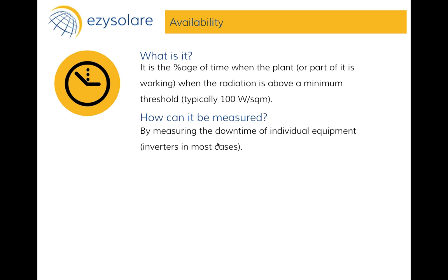Now let us look at how the penalties will get covered because of this dip in performance ratio. So the expected PR was 78.2, the actual PR was 75.4. The difference is 2.8%. If your tariff was 7 units, then this means that you lost a revenue of roughly 3,13,600 rupees.